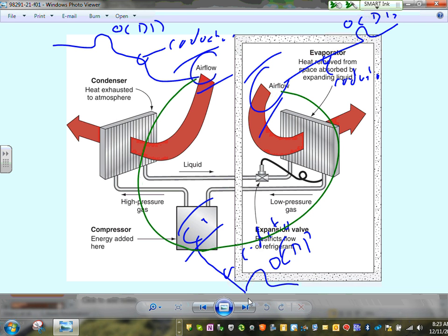We typically don't get into the control of it a whole lot other than connecting point to point. But you still have to provide power. Like you guys were doing the chiller, you need a fuse, disconnect, and a feeder to feed it. That's how we interface.